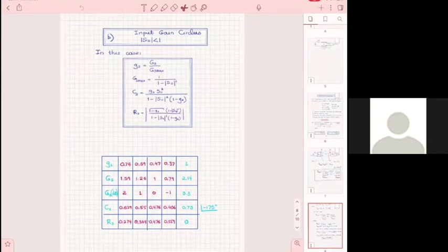Now, first of all, observe GS. Small GS is the ratio of the gain of your input matching network divided by the maximum gain they can get. And of course, both GS and GS max in that ratio are not in dBs.